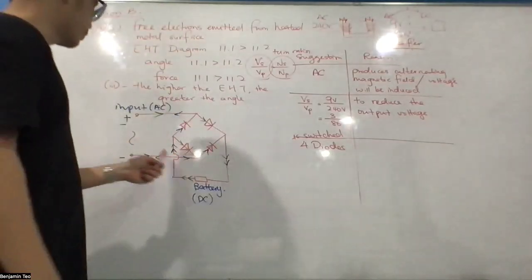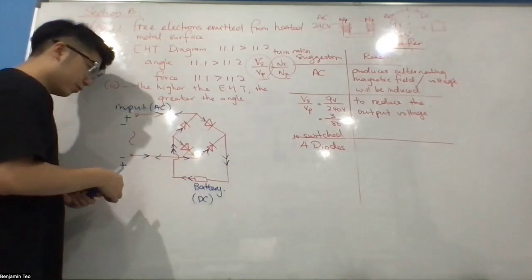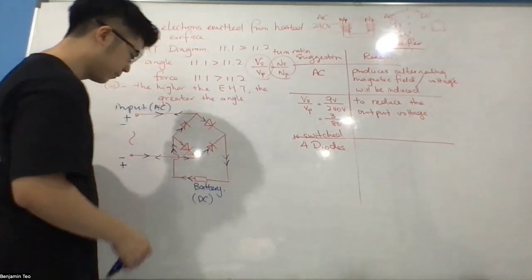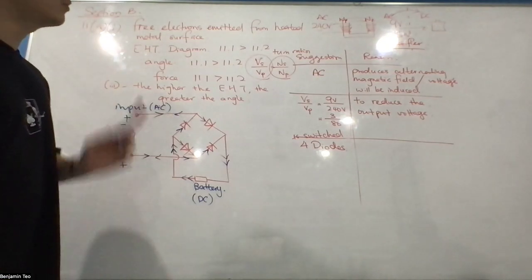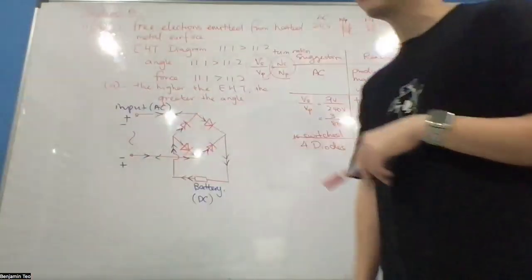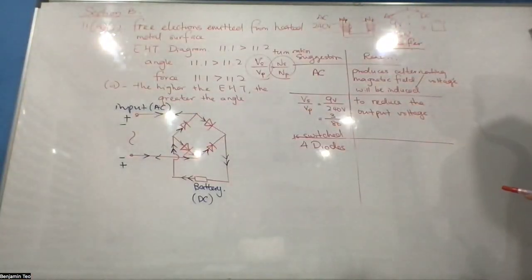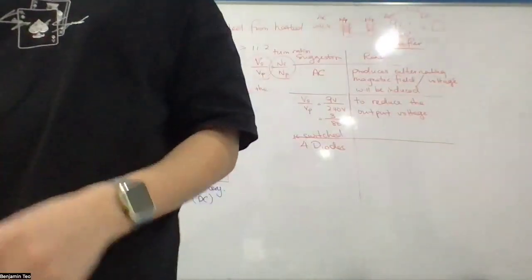So the battery experiences DC current. The main function of this circuit arrangement is to convert AC to DC. So your rectifier must be after the transformer. The transformer is used to step down to the voltage you want, then the rectifier converts it to DC. All such devices are charged by DC.